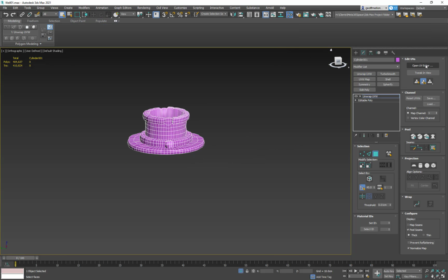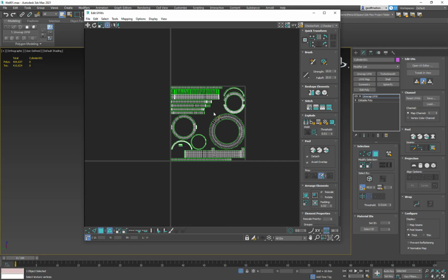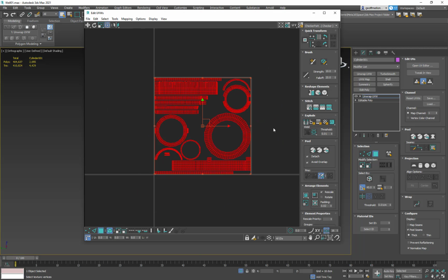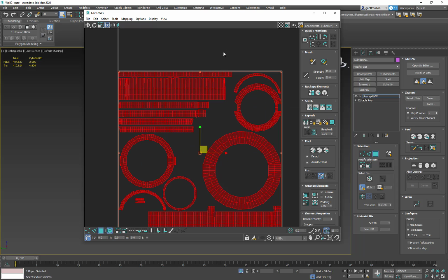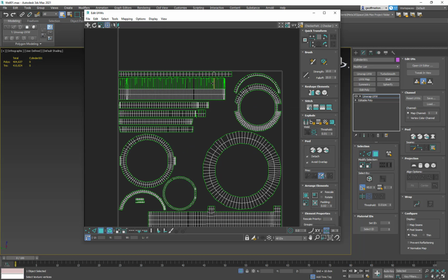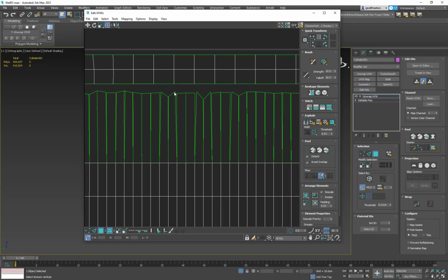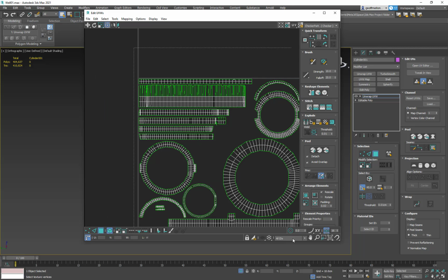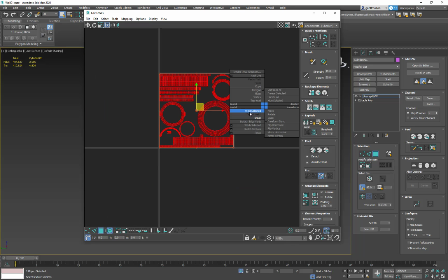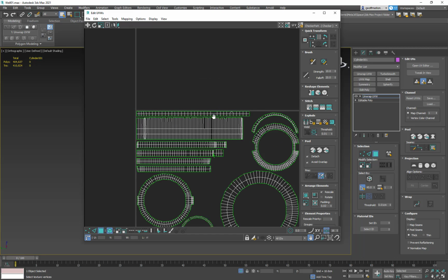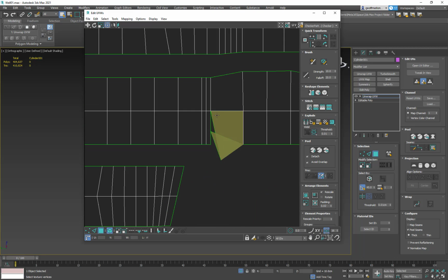Again, I can keep going on and on, but if you come back in here and look at your unwrap, it's still perfect, or it's still very well. So I can come in here real quick, because I've noticed whenever you see green stuff touching its sides here, it just means that these points aren't welded. So really easy fix is just Control A to grab everything, go in here and say weld verts, and you'll see now that the ones that are right next to each other are welded. And then we can clean up little things if you really want to.